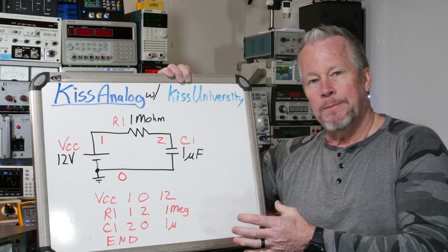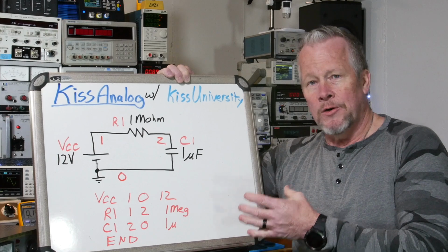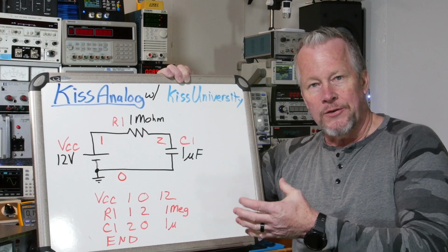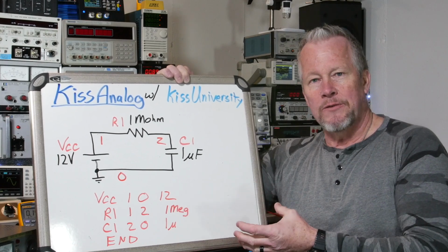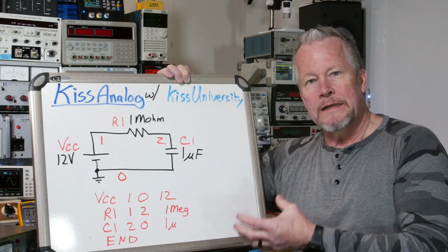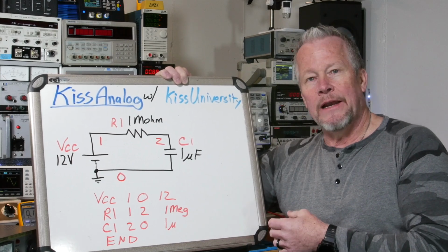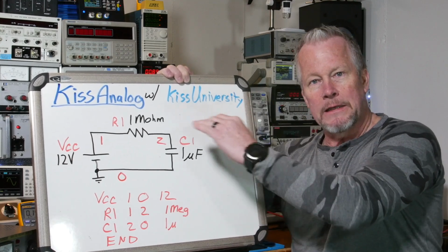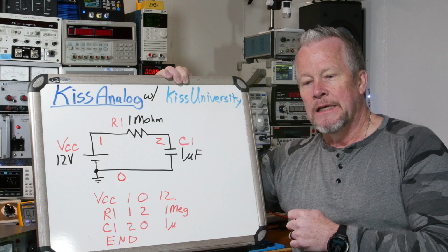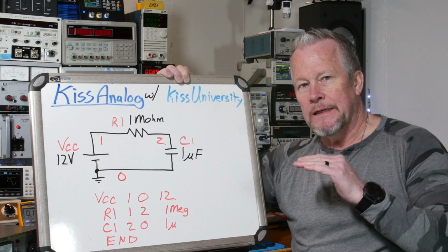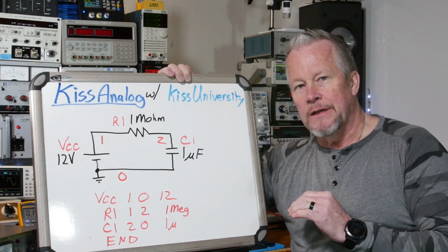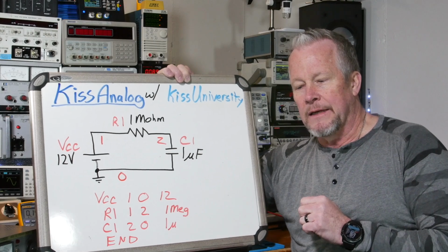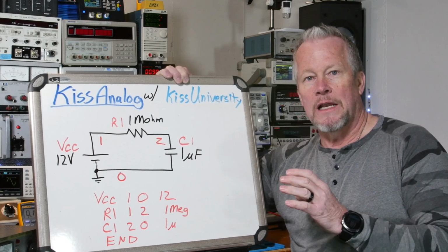One of the problems with SPICE is in the early days, not too long ago, until the computers got really powerful, it would take a long time to run a simulation. And another thing that would happen is, when I pointed out those nonlinear analyses, it means that all of a sudden you take a step function. And when that happens, the math and everything can go in la-la land.